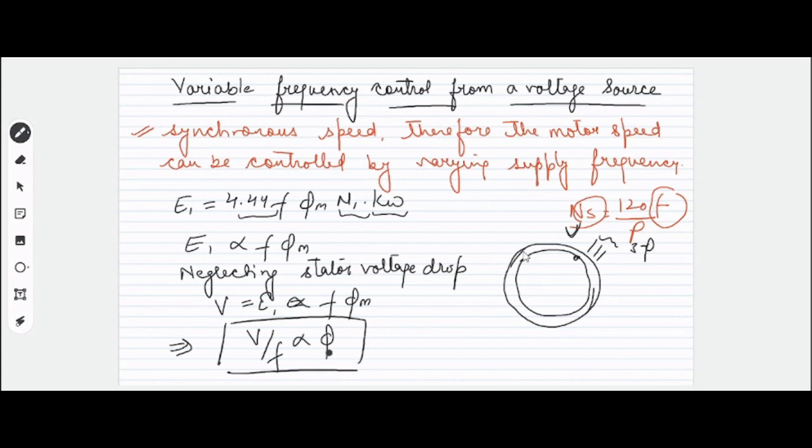Yes or no? Yes, sir. Right? So what we have learned is that by changing the frequency, we can vary the speed of the induction motor. But on this frequency, your flux also depends. In fact, it depends upon the ratio of V by F.